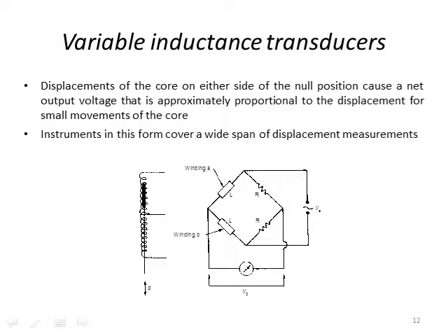And then if you're moving in, you can always set the movement to work in the linear range of the amplifier. So the bridge configurations for doing this displacement sensing are very, very useful. And you will see a bridge problem on the homework and the exam.